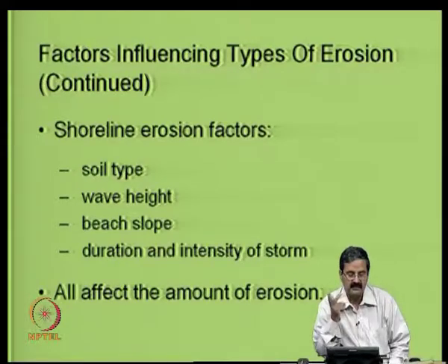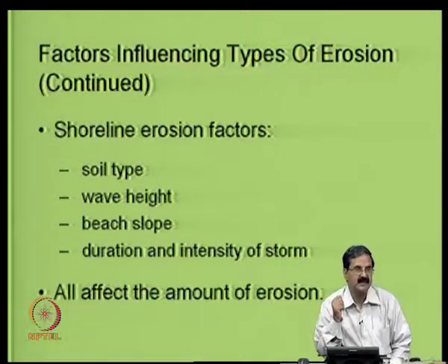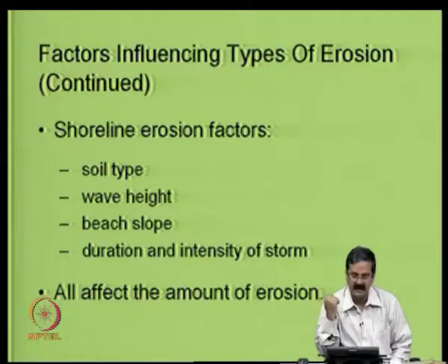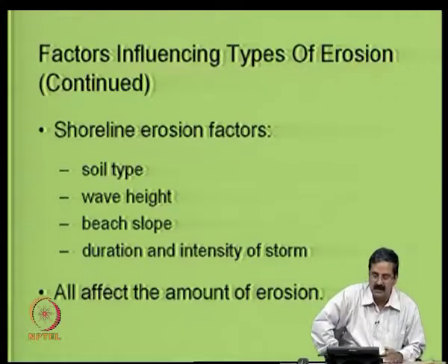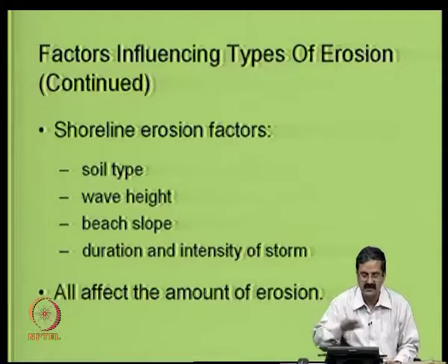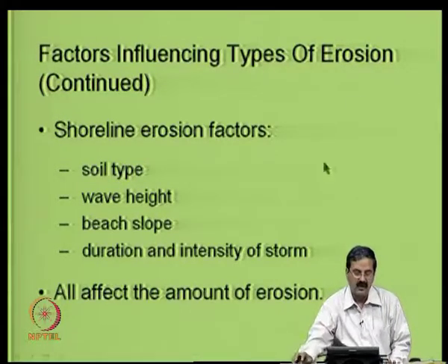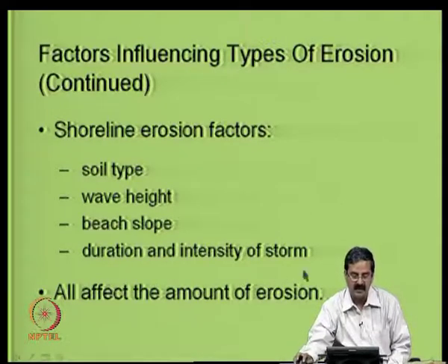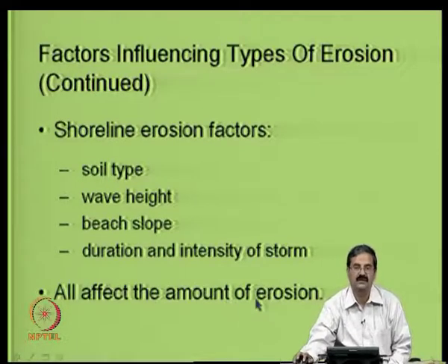In fact, as I said, erosion is even quite common on beaches, which we call shoreline erosion. Wave height is a serious variable, because the higher the wave height, the higher the force that it can transmit to the bund or slope. The beach slope is also very important. Duration and intensity of the storms, particularly in coastal areas, are all quite important. All of them affect the amount of erosion.